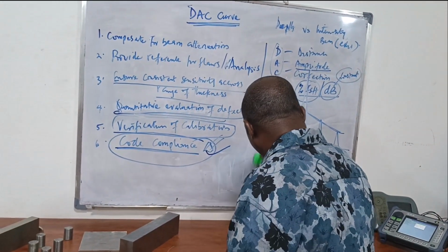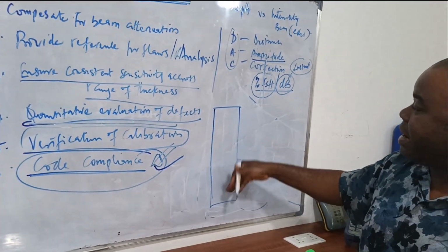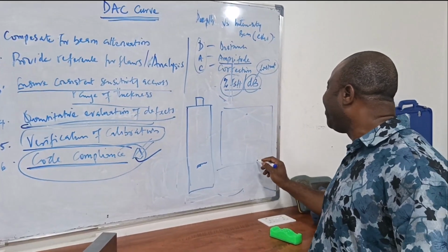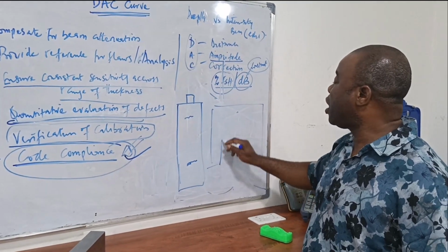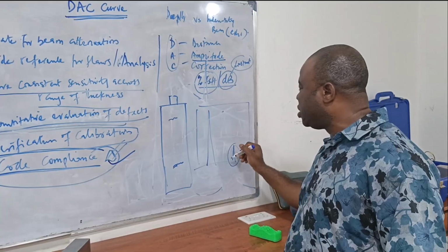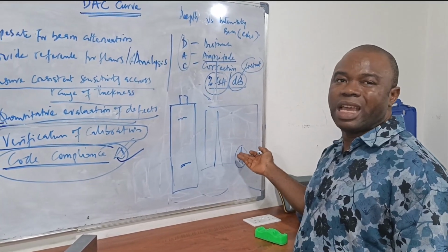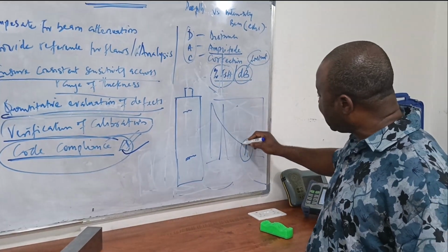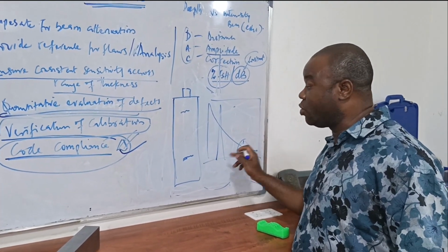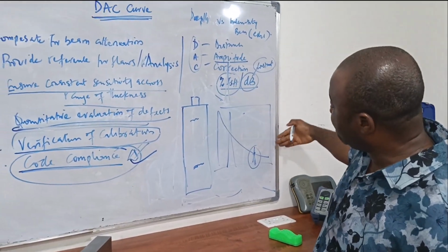Earlier on, I was talking about shafts. So if I have a shaft, a long shaft, and I'm trying to find a crack inside with a 0-degree probe. If a crack is somewhere around this area, on your UT screen we are going to see it as a very small level compared to when the crack is at this point, which we are going to see at a higher echo. What this tells you is that if I'm doing a scan on this shaft and I see a very small amplitude indication, it might just be a defect that we are looking for, but somebody might ignore it and say, no, that's not a defect, it could be noise or grass. But if you have a DAC that you have plotted and you know that your DAC echo at this point will always be at this height, and you are getting something crossing the DAC, it will obviously tell you that something is actually causing this echo. So because of that, you are able to consistently get echo heights and track them as your thickness is changing.